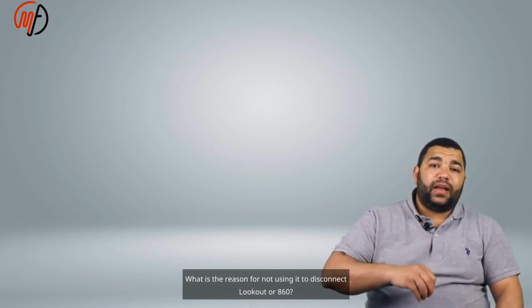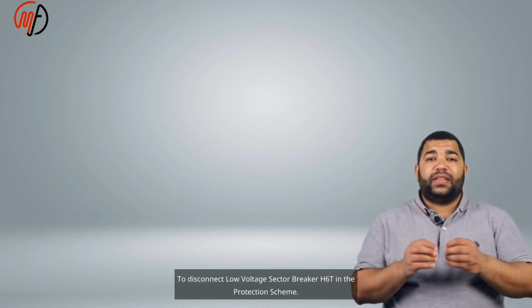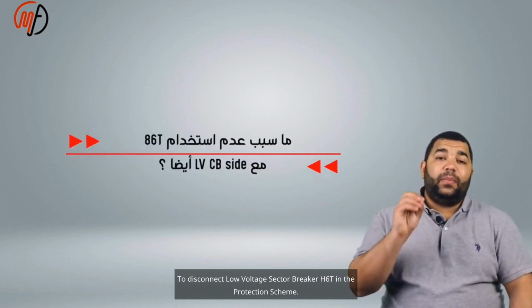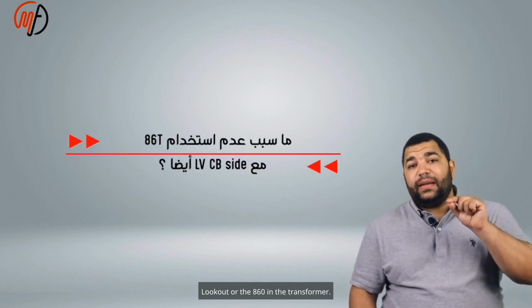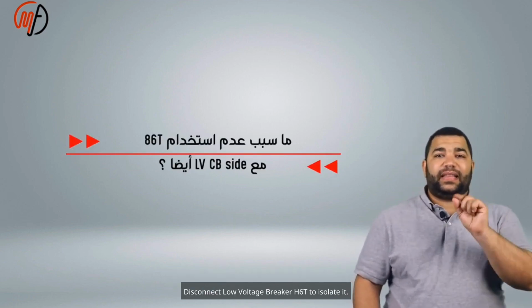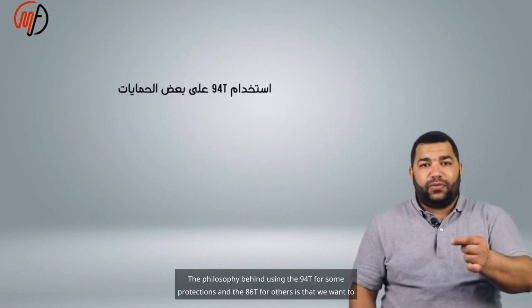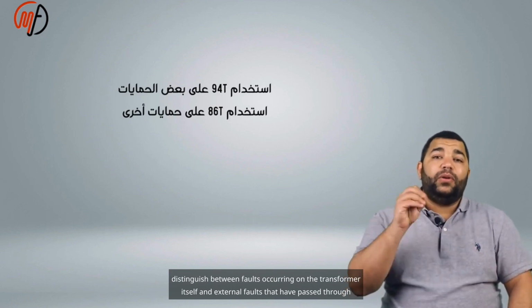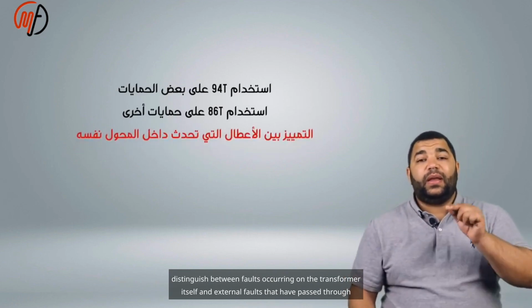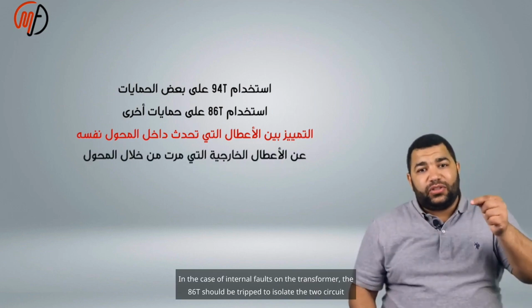What is the reason for not using the 86T lockout relay, the transformer lockout, to disconnect the low voltage breaker H6T in the protection scheme? The philosophy behind using the 94T for some protections and the 86T for others is that we want to distinguish between faults occurring on the transformer itself and external faults that have passed through the transformer.